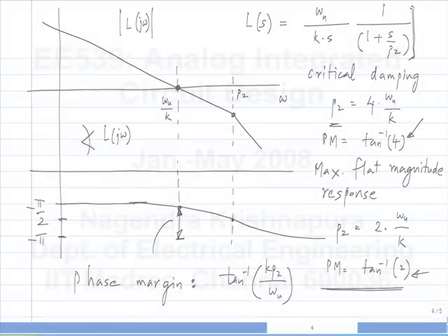But the problem in reality is that you will not have a second order system. So the notion of quality factor and so on is not very precise. Okay. But we do know that if things happen well beyond the unity loop gain frequency, then the result will be more or less a first order system with additional poles at these locations. Okay.